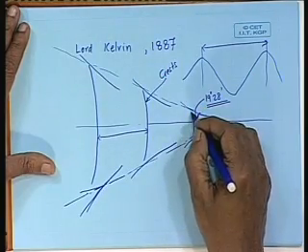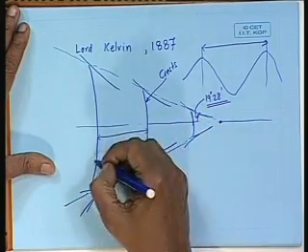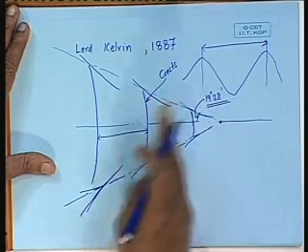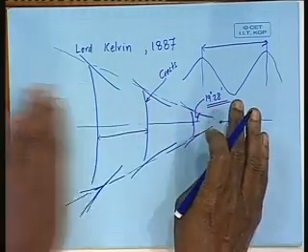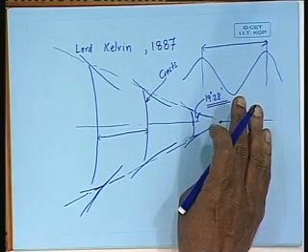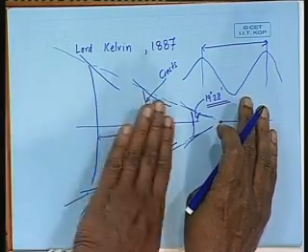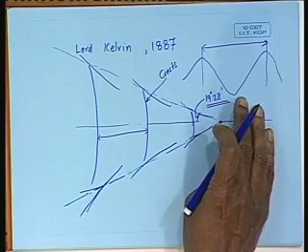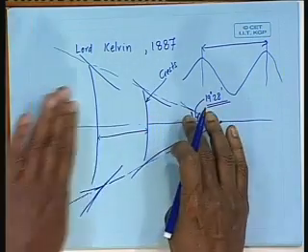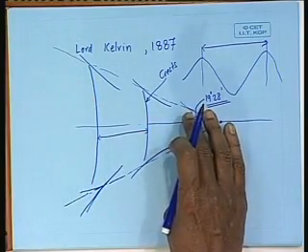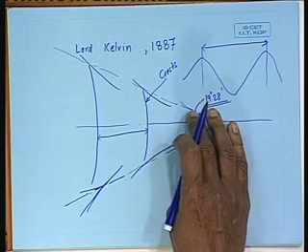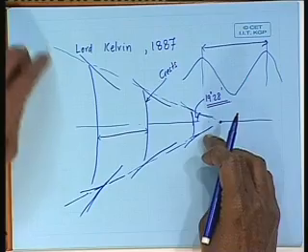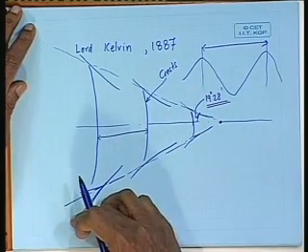Now, each transverse wave increases in length and therefore reduces in height as it moves away from the pressure point. So, you can imagine that as you go away further and further, the wave height will reduce, the transverse wave, and you will not see this far away from the pressure point. What you will instead see is these divergent waves.